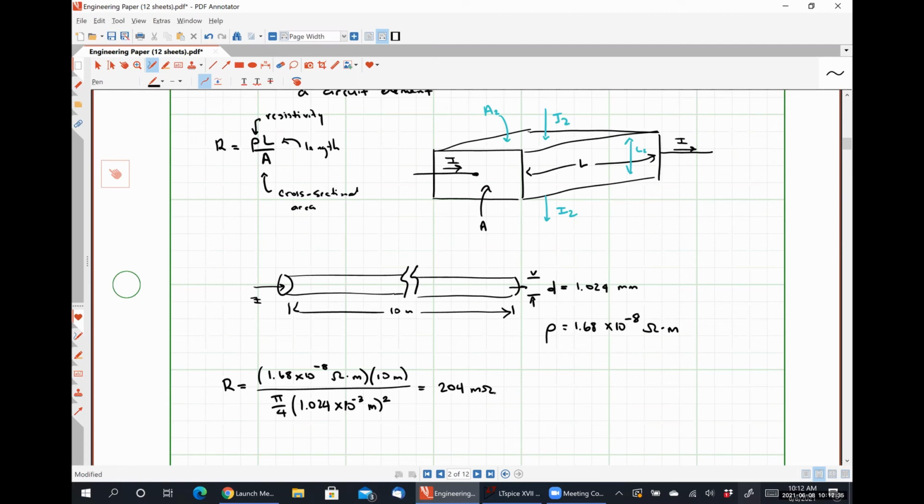Now the resistance of a 10-meter long length of AWG 18 wire is about 1/5 of an ohm. How does that compare to the size of the resistors that you used in, say, the Engineering 120 series? Anybody remember any of the resistor values that you happen to use? We had some values as high as 10,000 ohms when we wanted to save current in some circuits, and some as low as 220 ohms, 240, all of those values. So there was a range.